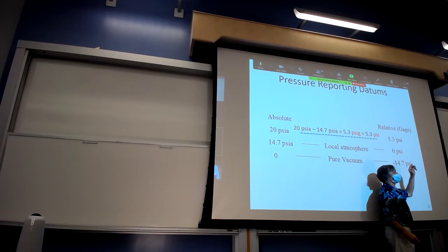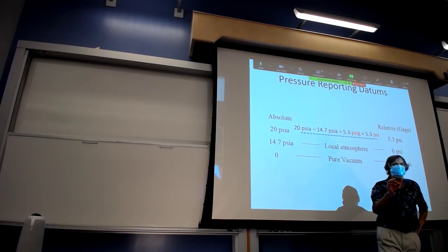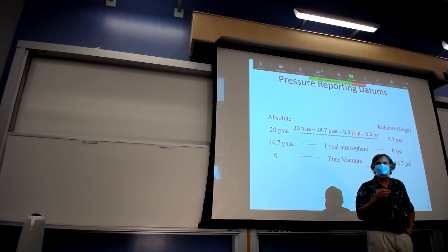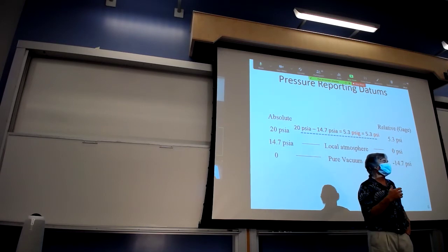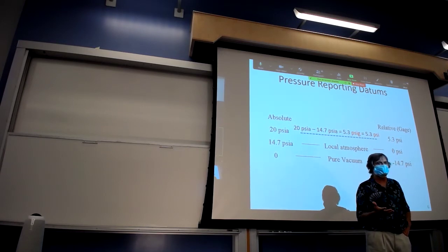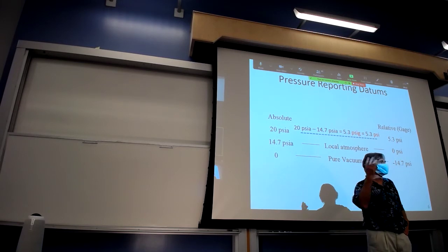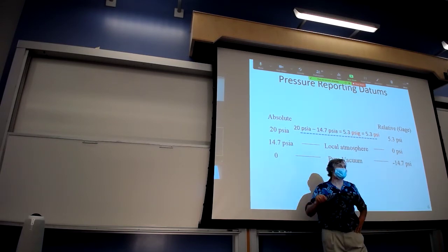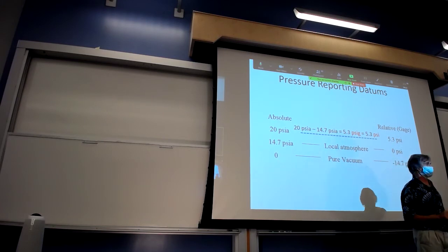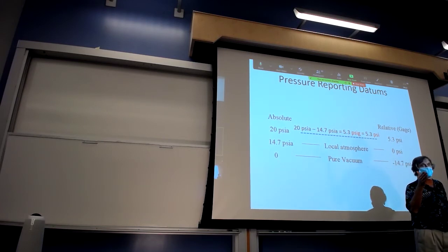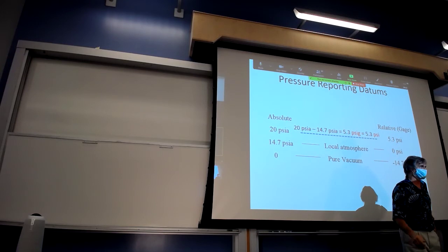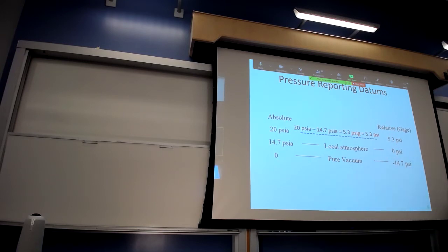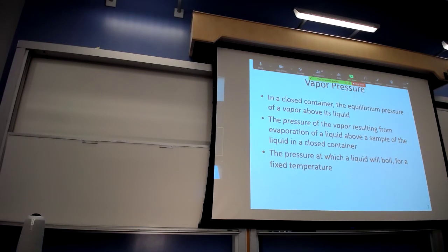And the difference is, in the old days, you would write PSIG. That means it's a gauge pressure. But since we conventionally almost always use that, and we like to be efficient, we just drop the G. So whenever you see the unit PSI, you know that's in gauge pressure. Whenever you see the units PSIA, you know that's an absolute pressure. And that means something. And it will come back to haunt us in later problems in this course. So that's what I wanted to start off with on pressure measurement data.